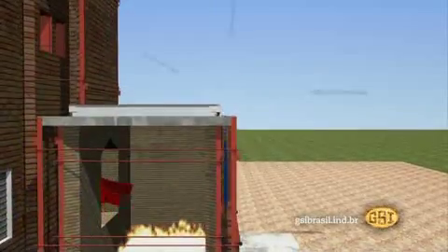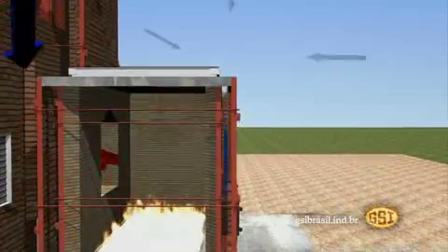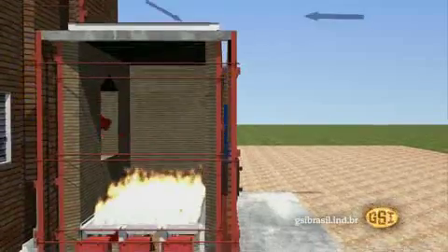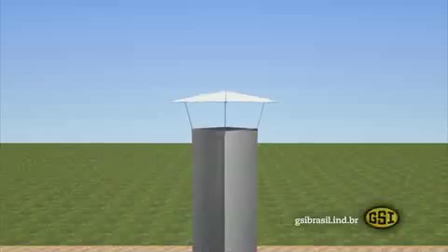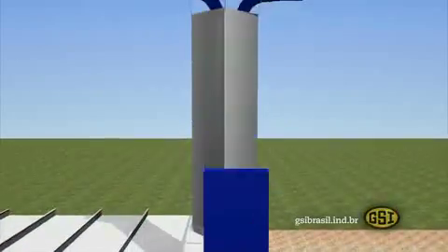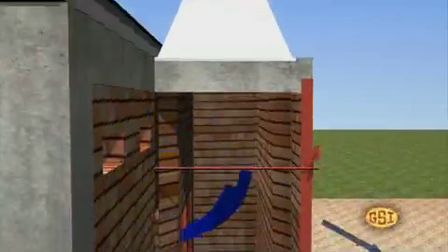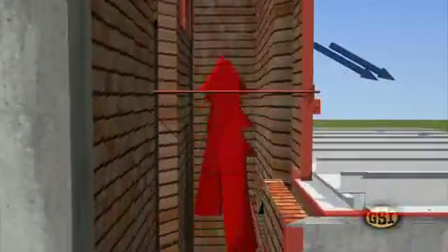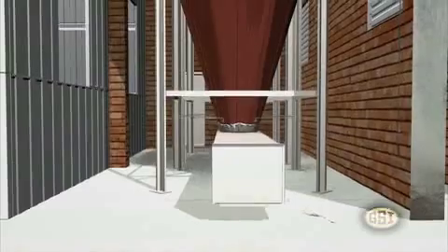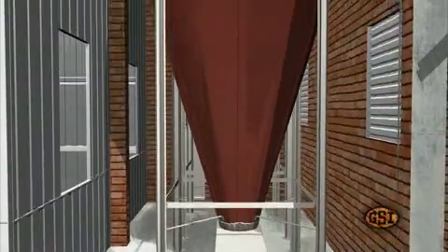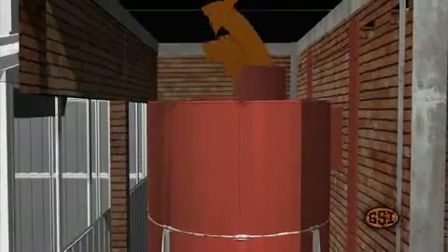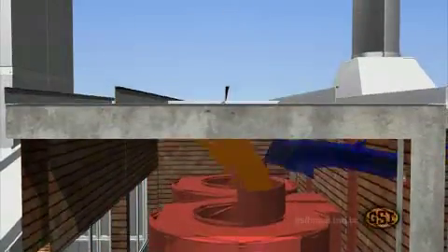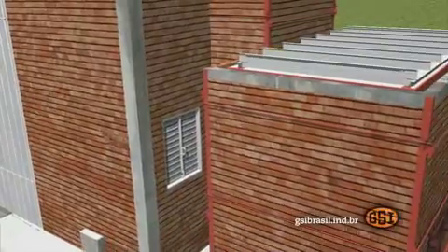The process dryer furnace operates at a higher temperature than conventional furnaces, approximately 700 degrees Celsius, thereby allowing better volatilization of combustible gases, providing greater energy efficiency and lowering combustion residue to minimum levels of soot and smoke. As a result, the drying air that reaches the grain inside the process dryer is cleaner than in conventional furnaces.